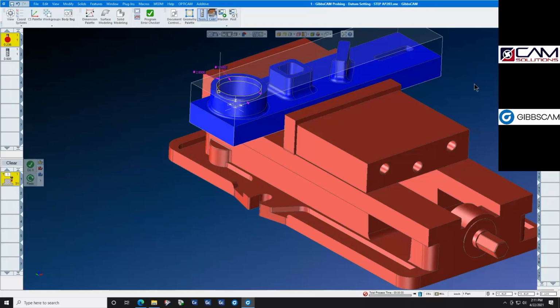Somebody's inside the machine with an edge finder. Somebody comes up and interrupts them, asks them a question. Hey, where's this tool? None of that happens because the probe is focused on its job. And when you push that green button, everything happens sequentially, and your part program becomes consistent from start to end every time, giving you more consistent results on your process.